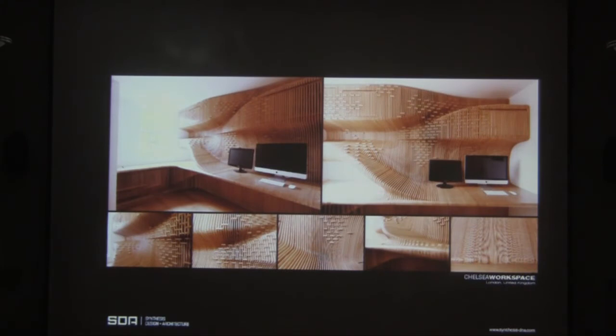One of the things that's really nice about this project is the edge finish, in terms of how that Europly develops this really amazing sheen through the laminates, but also this moire pattern that appears, this moire effect where you see between those slots. And because those slots are only fixed at the back end where they sit on those channels, at the front end we needed these horizontal spacers to lock them together.